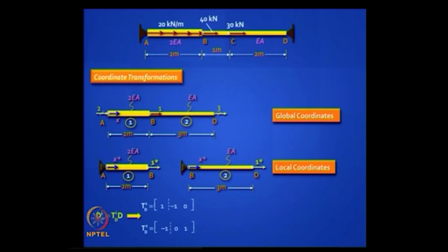It will be plus 1 or minus 1? Plus 1, right? What will be the elongation in member 2? Minus 1. It will go into contraction, right, because you are pushing it to the right, and you are not allowing D3 to move. So this first column that I get, when I apply D1 equal to 1, is plus 1, nothing but the elongation in element 1, and minus 1 in element 2. Is this clear? Makes sense?